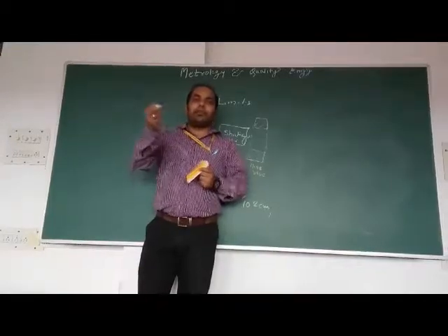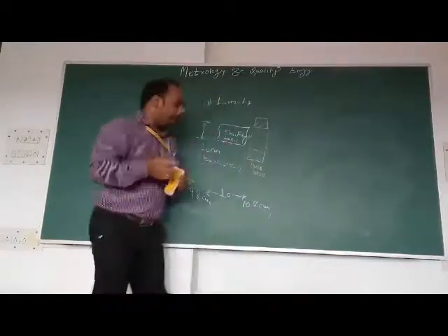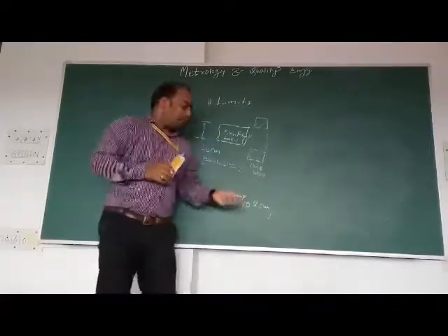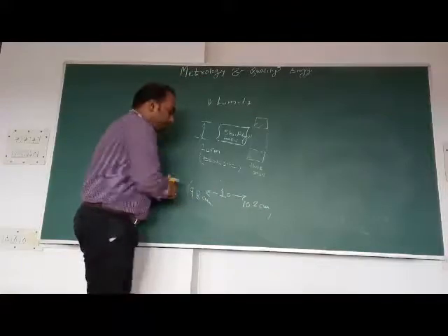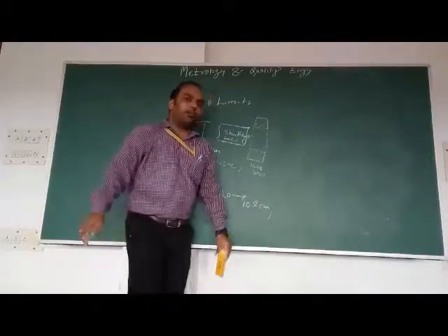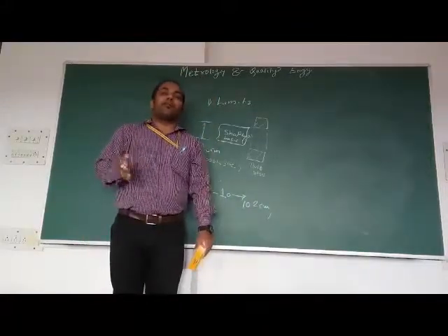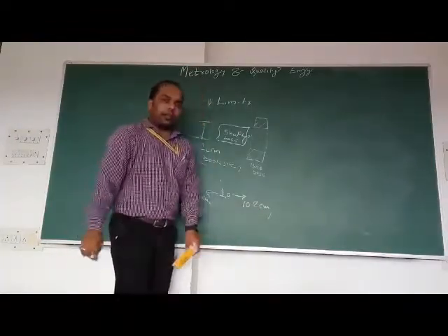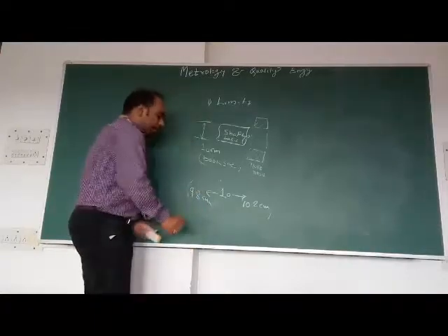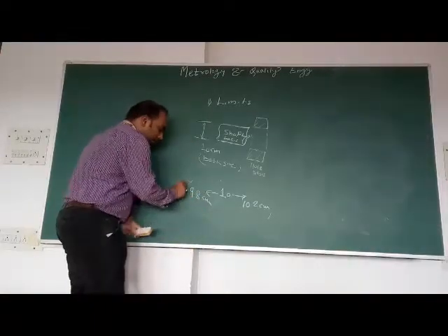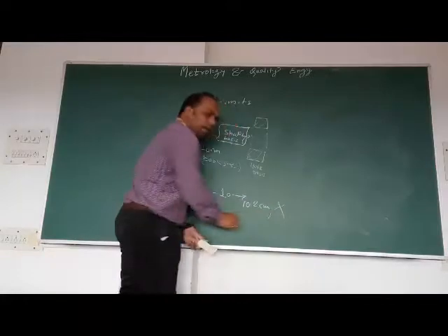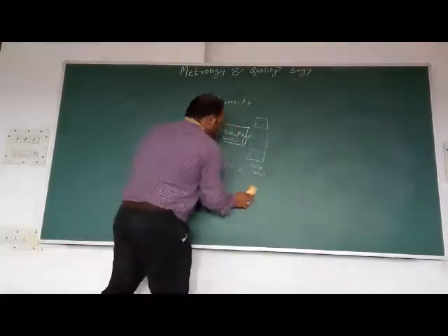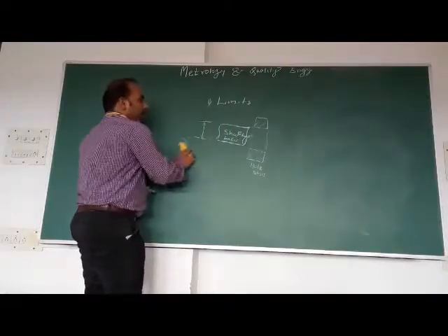During machining, if dimensions go plus or minus, the accepted components lie in the range between 9.8 cm to 10.2 cm. That means the permissible size is 9.8 to 10.2 cm, and that is what the acceptance limit is. Below and above these, components are not going to be accepted. Please keep that in mind.